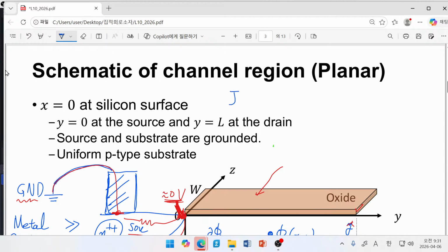So now Jn, that is a vector quantity, should be regarded as a certain conductivity times the gradient of quasi-Fermi potential. Everybody knows that this gradient is once again a vector quantity, and we have to have this one, q mu n n. Now we have the x directional unit vector and partial derivative with respect to the x direction.